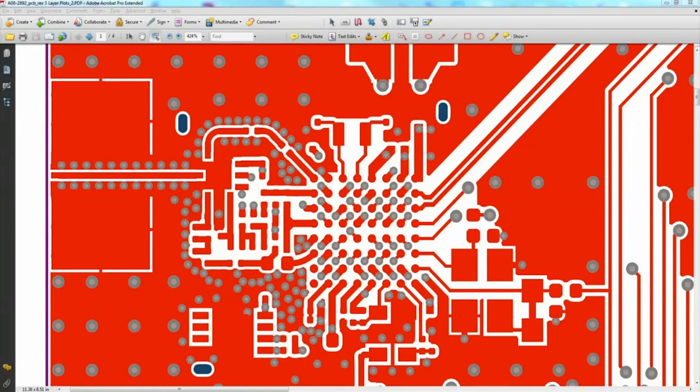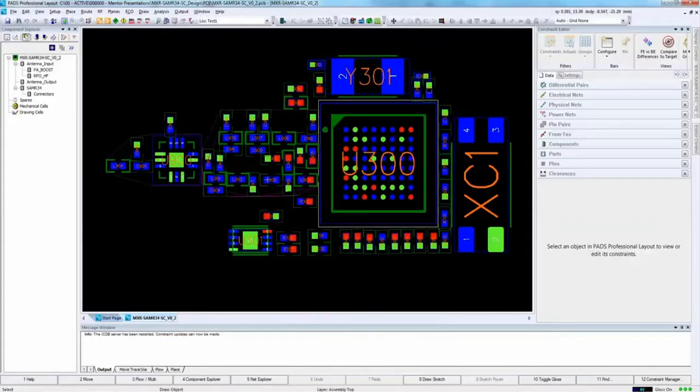And we have an example we can look at actually right here. Here's a layout where we have functional blocks. The antenna switch block you can see in a purple outline. I'm highlighting the front end block here. And this is a way to group, and something that PADS Professional I love about it. It really has been a great tool in grouping similar nets that have certain parameters that are similar, speeds, time of flight, and all of the items we had just covered.